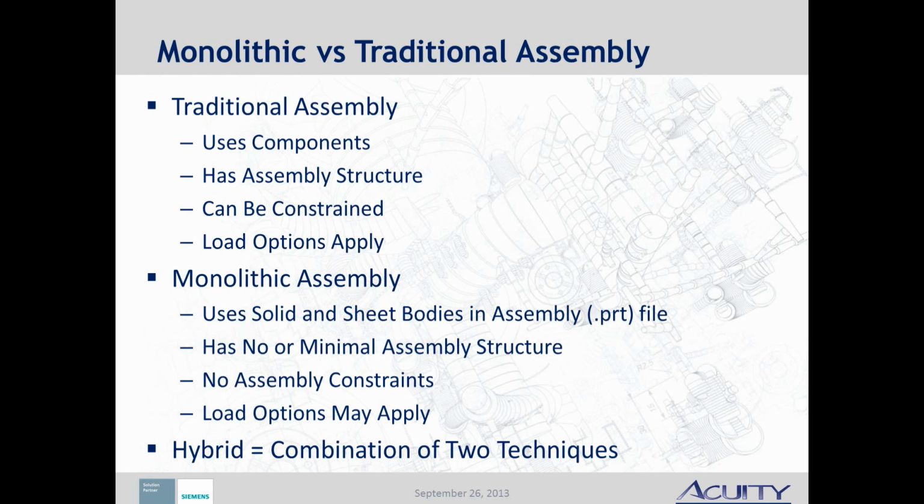So for some types of bill of materials, for example, it isn't really necessary to go all the way down to the lowest levels of detail. If that matches your bill of materials, monolithic assemblies can save you time on certain classes of parts that don't change or that are standard. Some examples of that might be motors, actuator cylinders, things that you'd buy that are small subsystem type assemblies would be a good target for the monolithic assembly.